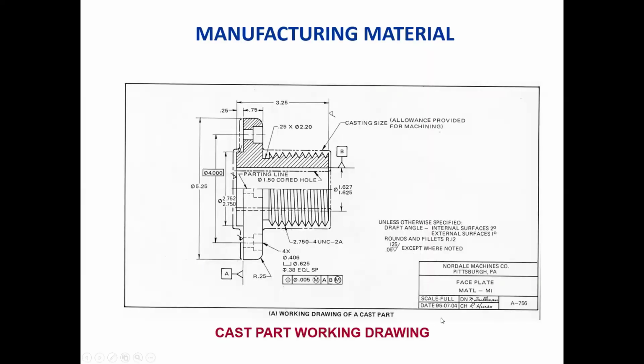What about a core hole? Core hole. What do you think that means? Like you're drilling a hole. Okay, sort of. You're making a hole, but when you core it, that means you're putting a chunk of material in the cavity of the mold before the material gets in there, and the material goes around that. So it's a core placed in the cavity.